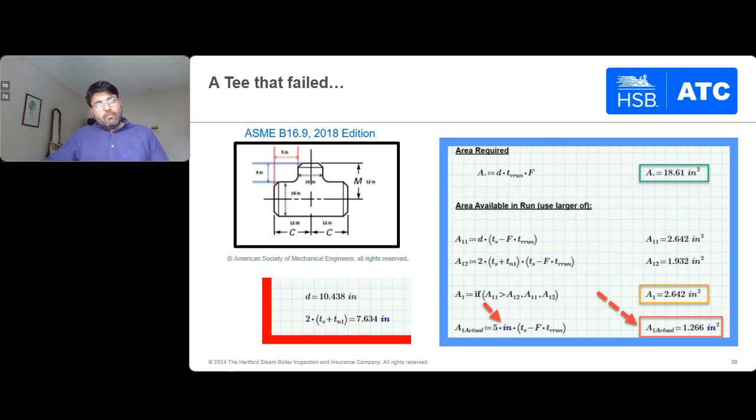Now, when you think about it, some of you may have done calculations, and this is often a topic that comes up. The code would establish the maximum limit. What if I don't have that? Especially when you have overlapping reinforcement. So of course, you don't have to have this, but if you don't have it, something has to be offset there to really maintain that required area.